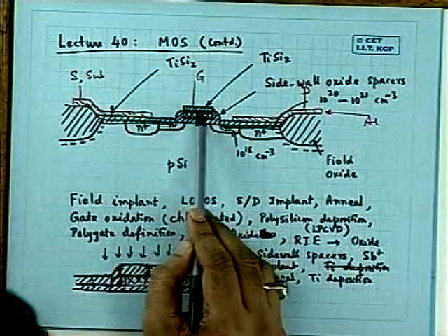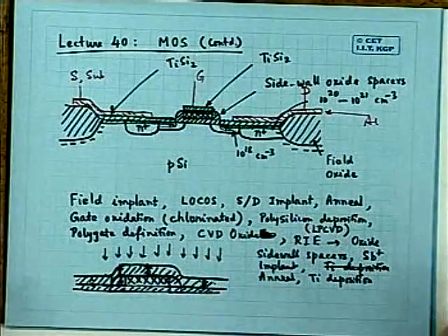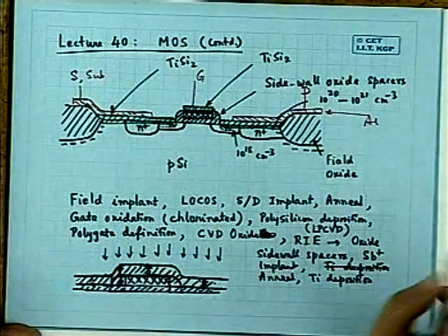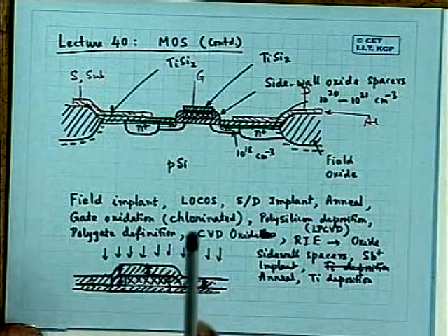But I have told you that I have missed a very important thing which I have discussed in the class. What is the benefit of this antimony implantation? It is a self-aligned process. Automatically the gate is defined. You don't have to do a separate alignment for defining it, because of self-aligning. I'm asking you a very specific question. Which step have I omitted that I should not have? Because I have discussed it in the class.